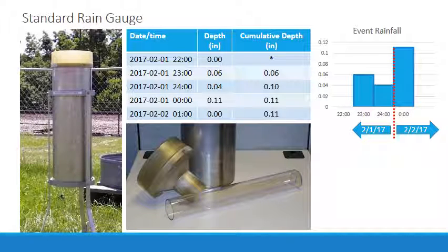The standard rain gauge has a diameter of about 20 centimeters or 8 inches at the top. Once the water is caught, a funnel conducts the rain through a narrow opening into a cylindrical measuring tube that has a cross-sectional area only 1/10 as large as the receiver.